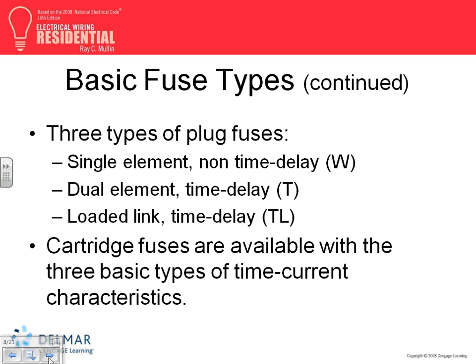The plug-in ones are different. All these W and T and TL, all these guys, I'm going to leave this one. Don't ask me too much about the differences. First of all, we don't care too much about the single non-time delay fuse. The W is called non-time delay fuse, then there is time delay fuse, and loaded link time delay fuse. A non-time delay fuse, guys, just sees a short circuit and bam, it opens. It melts. A time delay fuse, you use it in motors. It sees a high amount of current, sits for 10 seconds, and then it opens.